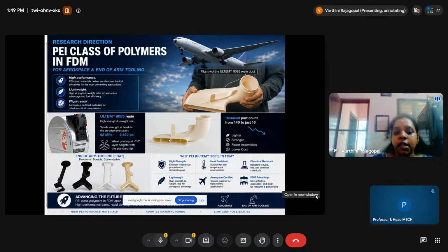What they have done is they have removed the solid material in this bracket and kept the material only where the stress is needed. They took this solid design and did a stress analysis to determine where the stress will be distributed based on the given loading conditions, and only in those areas they have kept the material. In the remaining areas, they removed the material. So this is the final result. Whatever application they developed the solid bracket for, this optimized design is going to work. That is known as topology optimization.